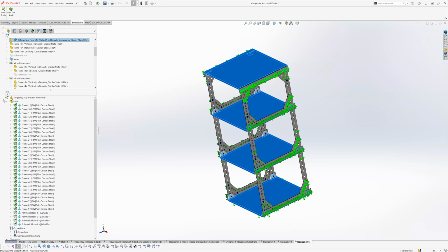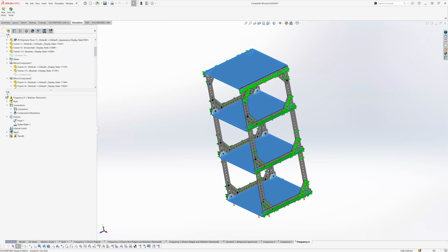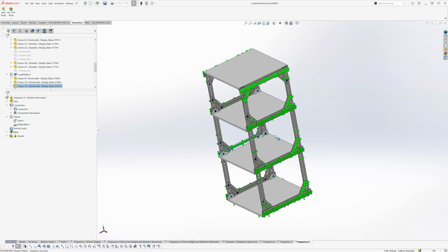And then what we can do now is build one mesh and run. Technically, we don't even need to mesh. We just need to run. That's why the mesh is still intact, because we have not actually changed any of the geometry. The only reason you need to remesh, like why we had to remesh between the first and the second time with the washers and the no washers, is because the geometry had changed. The washers were there and then the washers weren't, which means the mesh has changed. But changing something from rigid to deformable doesn't change the geometry. It's just changing how the geometry can behave, if that makes sense.